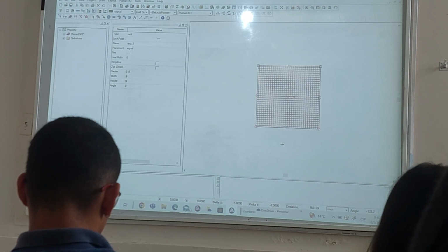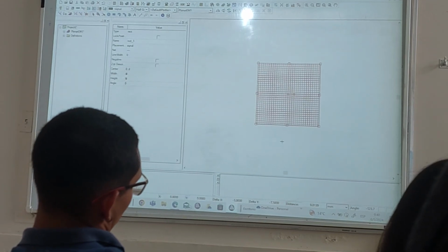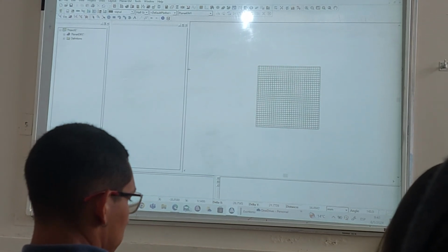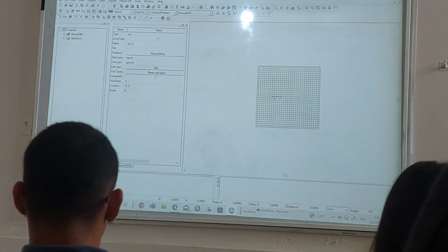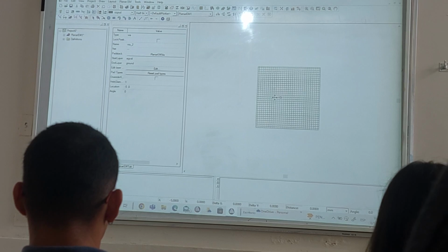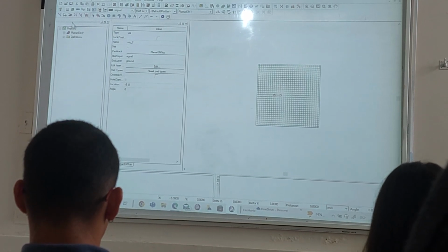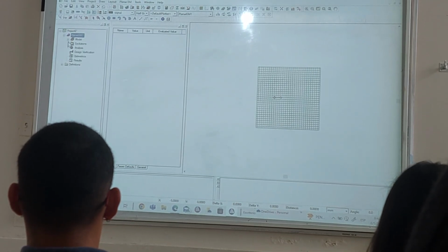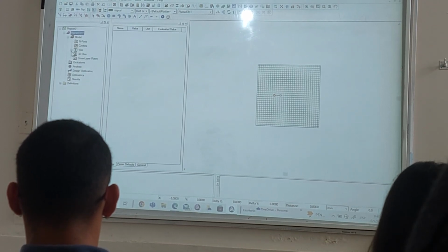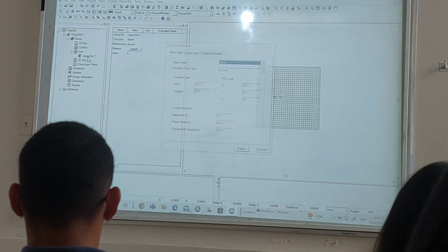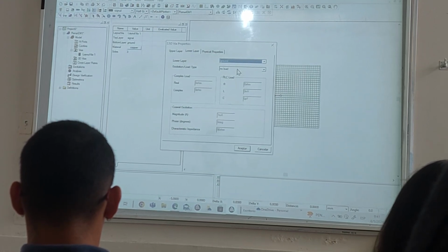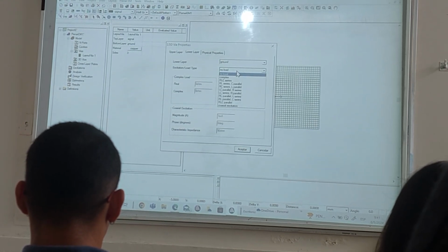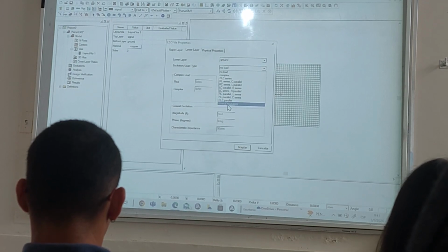Then we change this value, you see the antenna is smaller, and as we did in the last lesson, we put the coaxial cable directly, this via. On the left side, in the model, you have this via, and you put as properties, you go to the lower layer, and you set it as a coaxial excitation.